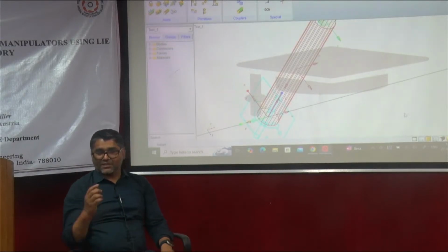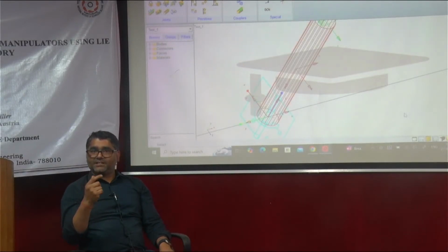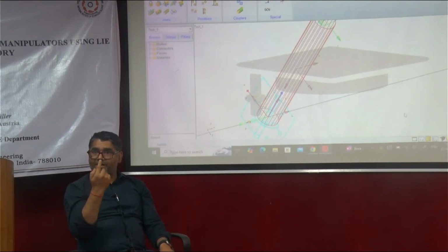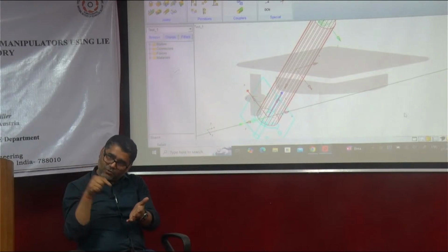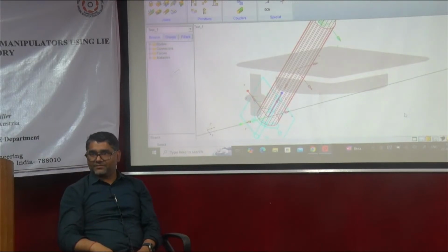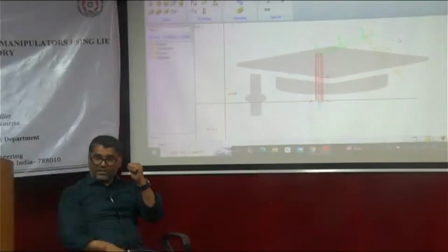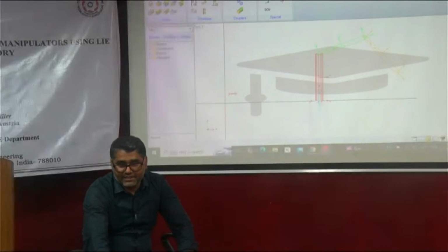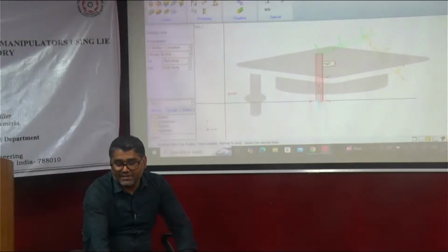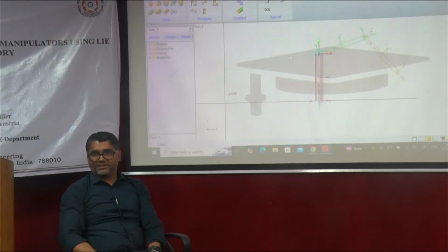Now you see, the z axis rotation means it will rotate uniformly. It is a y axis rotation, but about its own frame it is the z axis rotation. Okay, so now z. Again we'll choose this part and part 3, and this is the location where the revolute joint is needed, and click. So this rotation is correct, the direction is correct, so no need to change.